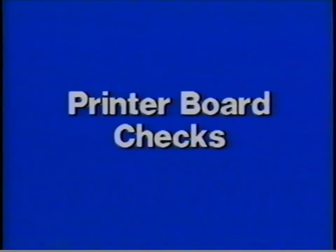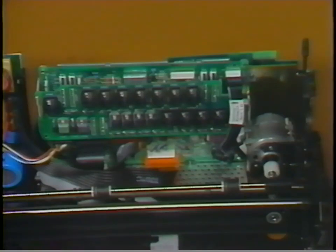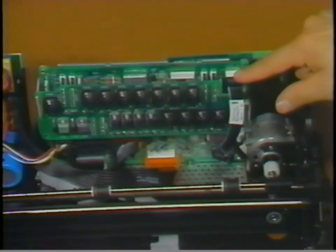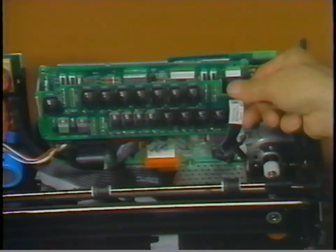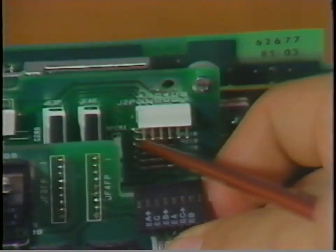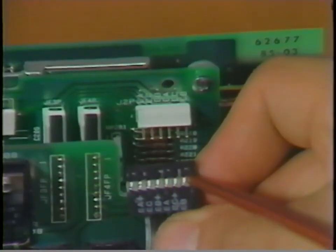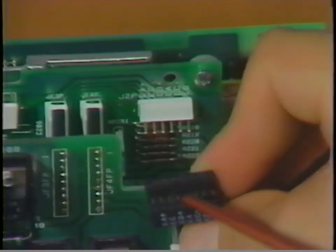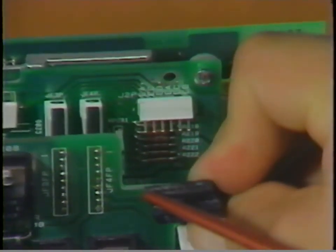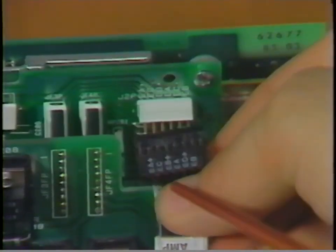In this section, we will discuss some of the diagnostic checks done on the printer board. First, let's locate the connectors on the printer board. The platen and feed rolls have been removed to make the parts easier to see. This is the transport motor connector J2P. Note that there are 6 pins on the printer board and 8 pins on the connector. The pin on each end of the connector is blocked so that the connector cannot be plugged in wrong. The connector plugs into the board with the printing on the connector facing up.